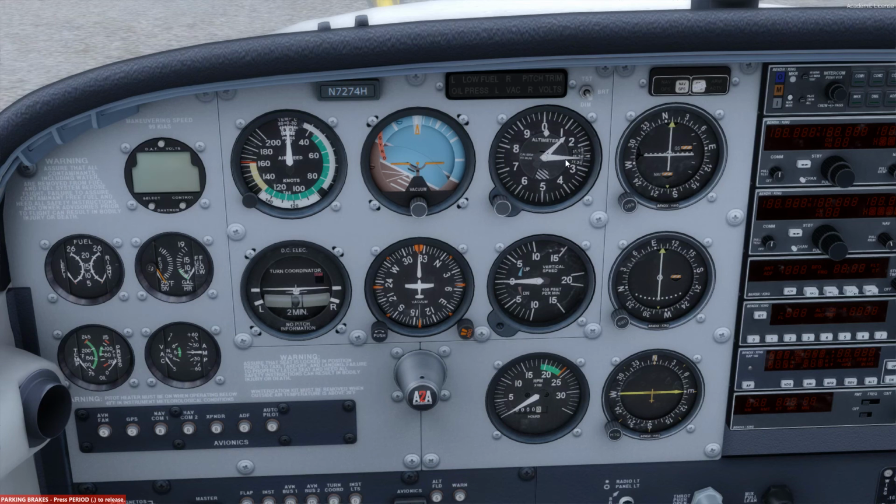So right now this altimeter is showing 1,250 feet approximately. And now it's showing 1,100 and 1,000 feet. And then one more thing to point out is this little diamond here. This diamond is tens of thousands. So since we're at just above 900 feet, we're way below 10,000 feet, and so it's a lot closer to the 0 than the 1. If we're at about 12,000 feet, this diamond would be over here, somewhere in between the 1 and the 2, closer to the 1. Next, we have the vertical speed indicator.